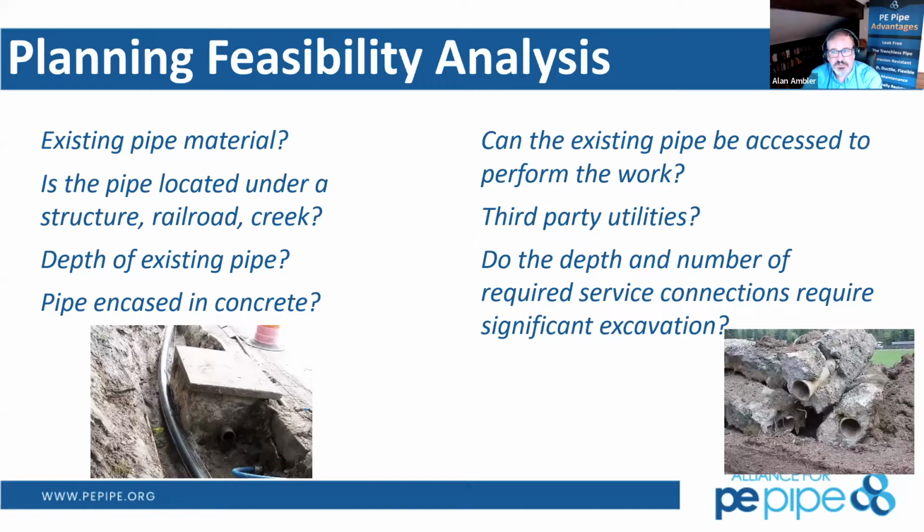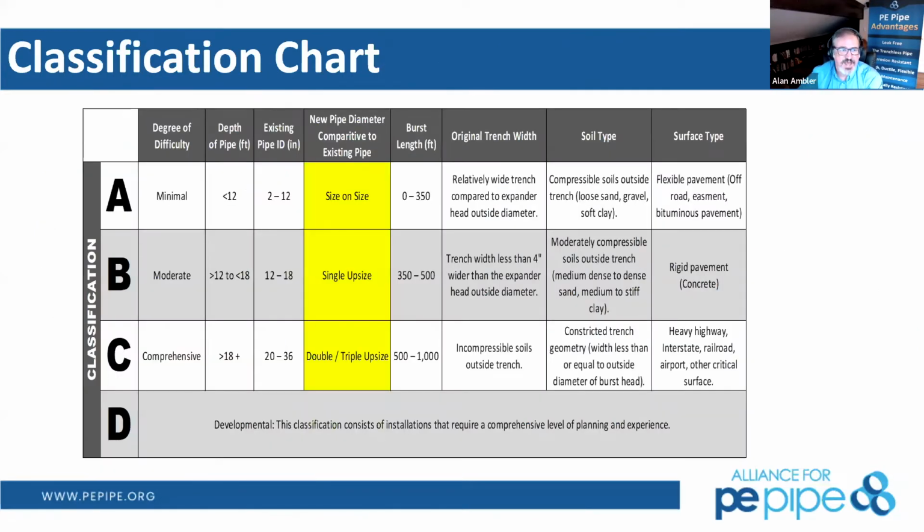Some of the things that we're going to look at to deter pipe bursting, or if we cannot access the pipe in any way, shape, or form, i.e. it's underneath a railroad, underneath a water body, underneath someplace we simply cannot dig down and access it, then that may very well preclude our pipe bursting project from happening.